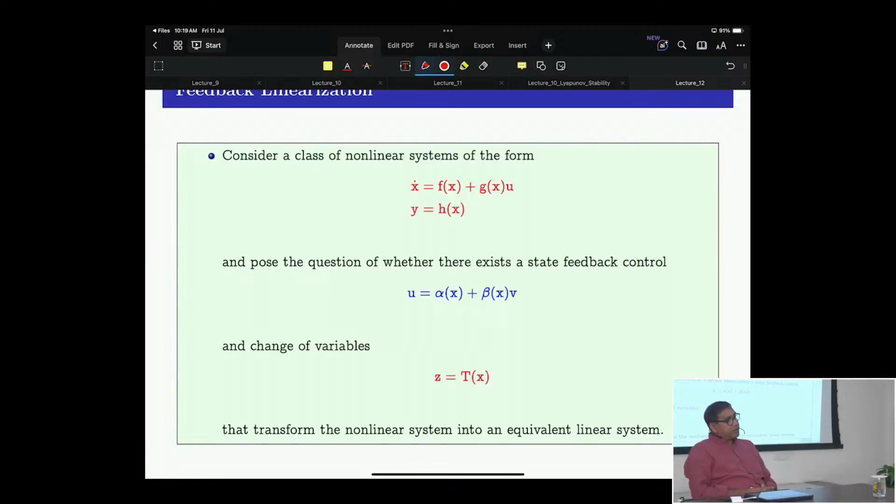If you want to design an adaptive self-tuning controller, you represent the system by a discrete parametric model, because the derivation starts from discrete parametric models. If you want to design a state feedback controller, the system must be x dot equal to ax plus bu, not a parametric model, right?